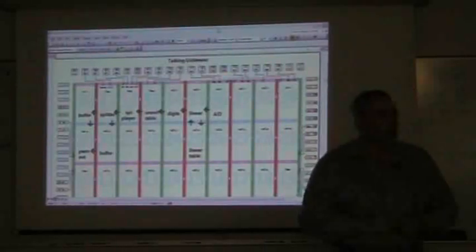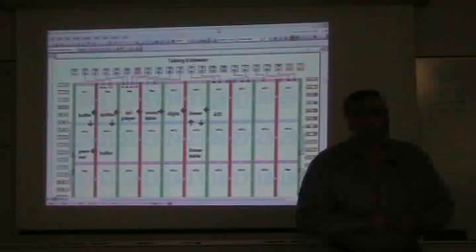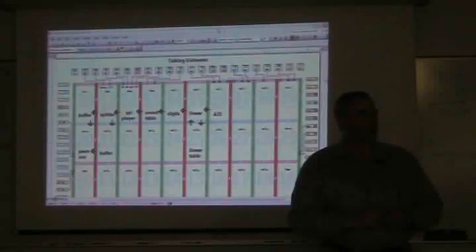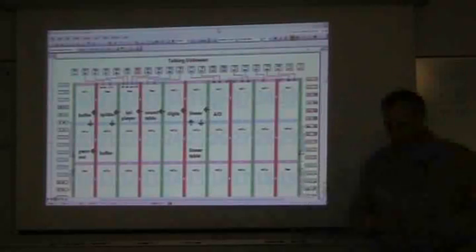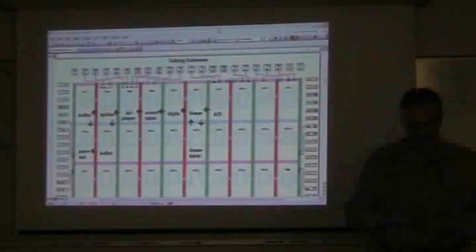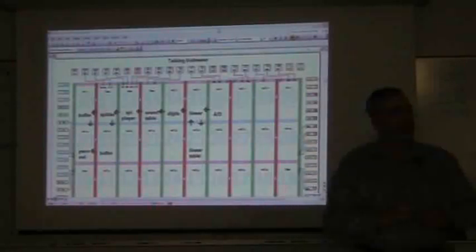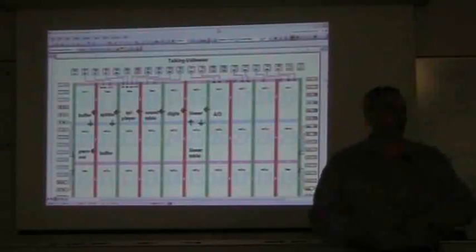One more question. Regarding the A to D to linearizer transition, I noticed that in the documentation, they recommend that you XOR the ADC reading with 155 hex. If you calibrate the linearizer table, do you still need to do that? Yeah, the original worked one way, and we made some changes to it, moving in one case from hardware to software, in the other case from software to hardware, so it would work better. And now you're required to do that in software.